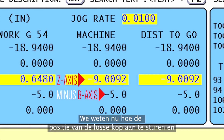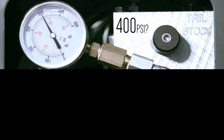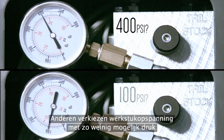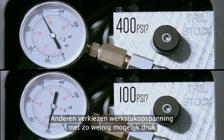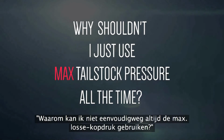So we know how to control the tailstock's position and protect it from crashing. We're ready to clamp our part. But one question remains: how much tailstock pressure should we use? Many machinists believe it's best to use as much tailstock pressure as possible so the part doesn't come out. Others believe you should hold your part with as little pressure as possible so you don't deform your part. You might be thinking, well, why shouldn't I just use max tailstock pressure all the time?